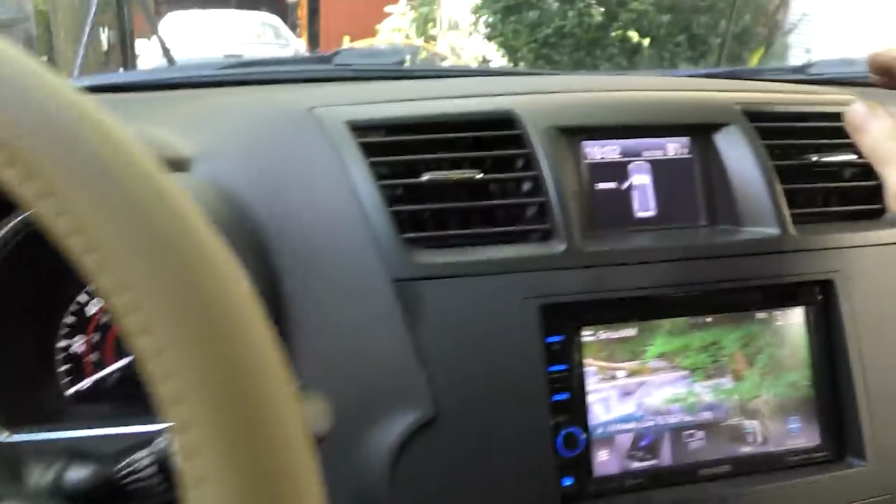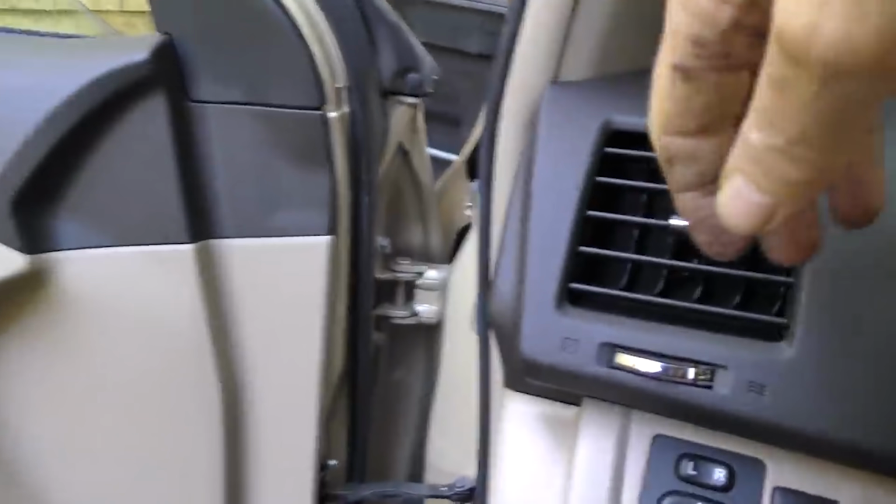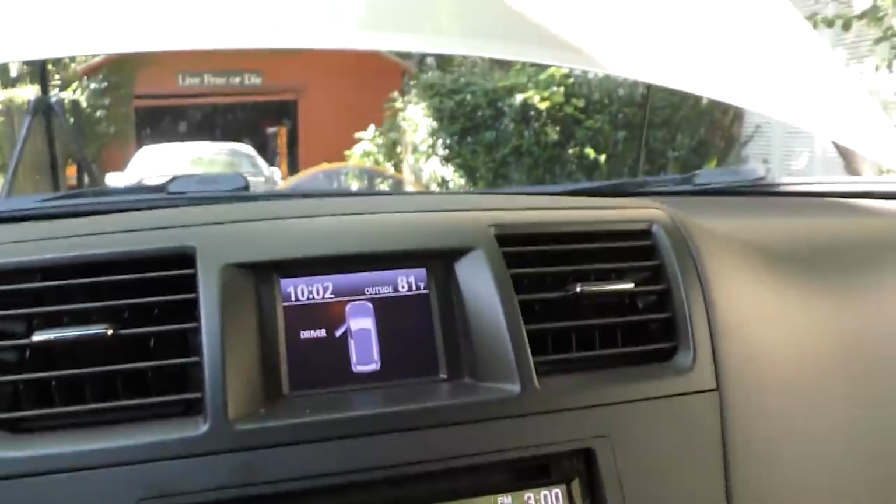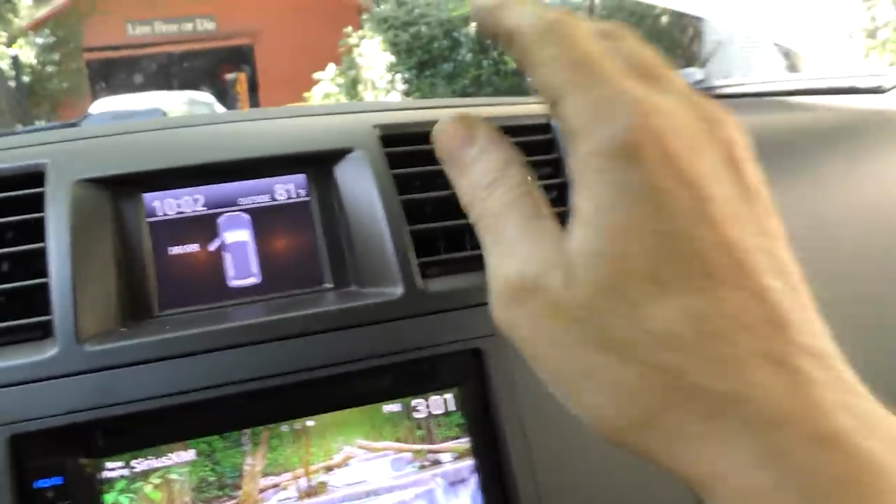When I go inside, this side is cooler than that side. This is outside air temperature. This is a little cooler. This is somewhat cooler, and that's a lot cooler over there. When you're low on refrigerant, evaporators in there will often blow a little cooler on the other side. So we're going to add some refrigerant and see what happens.